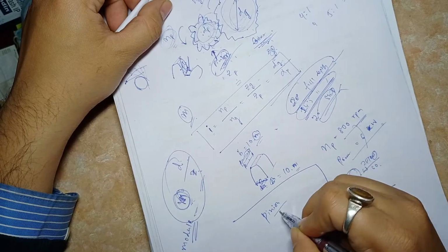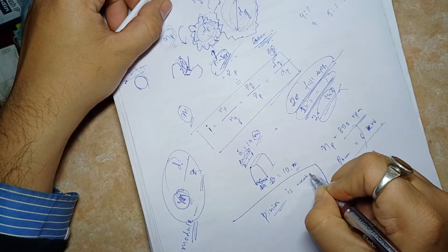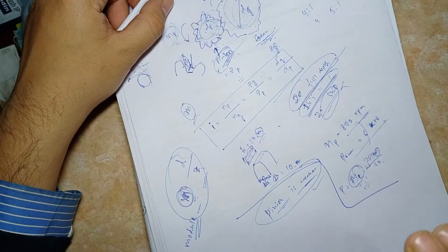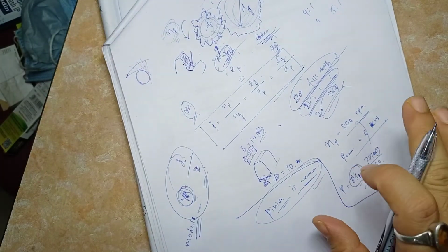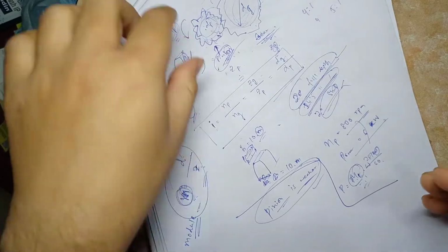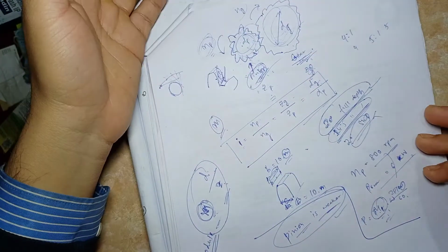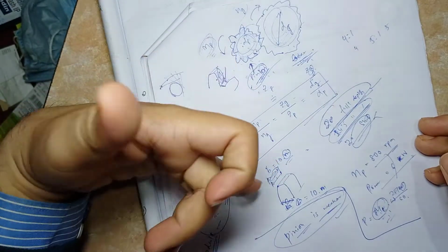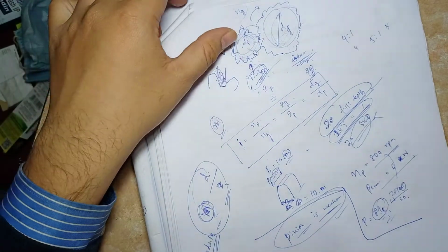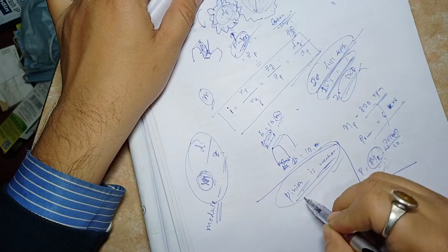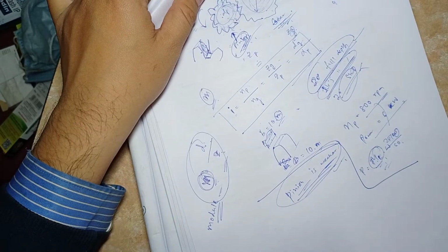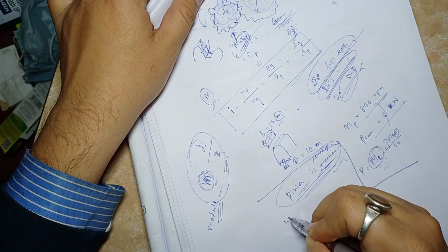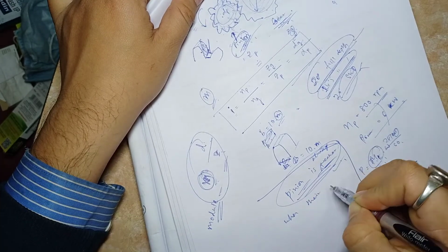We consider the pinion weaker than the gear, so we design the pinion to be safe to withstand the load, and the gear will automatically be safe. But this condition is valid only when the materials are the same.